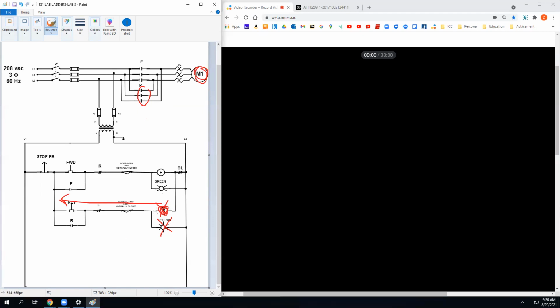No, the coil. Now you could look at the limit switch, and you would probably be right. But there is a chance that you would have voltage here and have voltage here and nothing's working, which means your yellow light's probably burnt out and the coil on the reverse side of that contactor is open or what not, so you're not working.